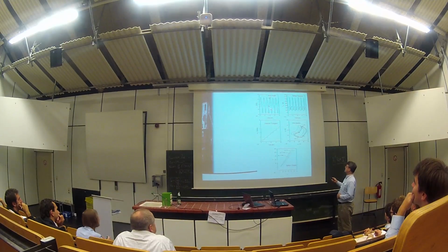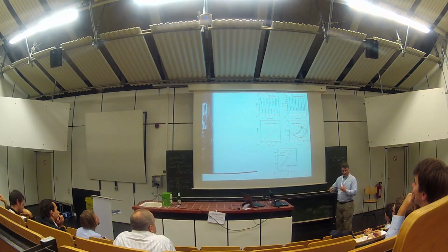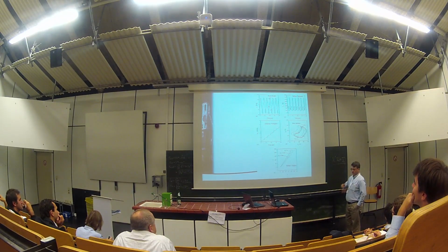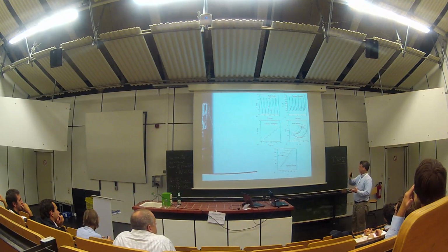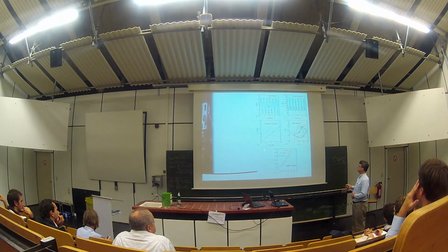Arm angle versus time here. You see we predict the periodic motion of the arm with a frequency of about a cycle every 4 seconds. Tether tensions, we picked our tether based on those. You get these peaks of maybe 1,400 newtons. Here we're at about 500 newtons. So 100-pound forces on these tethers, usual. Here's the volume pumped versus time, and we'll see more results on that.